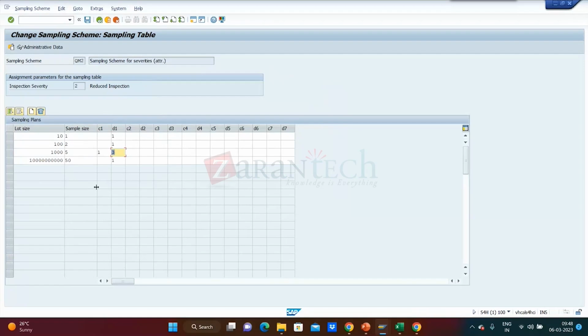You're getting my point, right? Yes. If one sample is rejected, still you can accept that particular characteristic. From 5 samples, if one sample is rejected, still we can accept that sample. That is my acceptance criteria. Okay. Rejection criteria. If 3 characteristic is rejected, then reject it. Okay. Otherwise, still it is accepted. So these kind of criteria we can define.